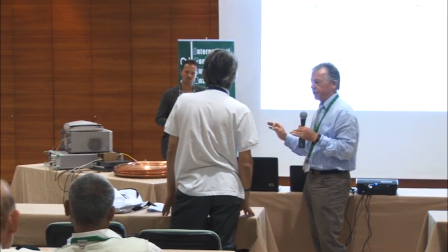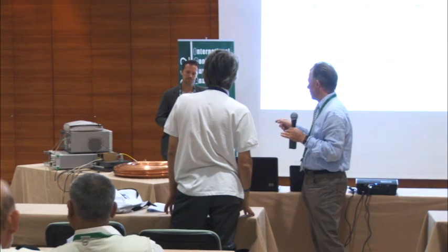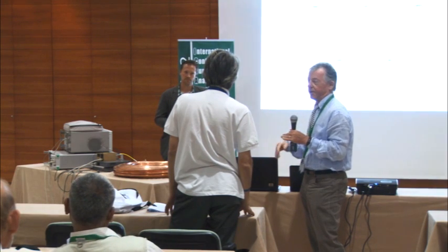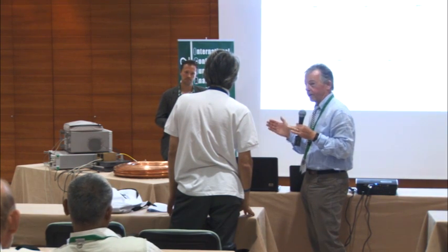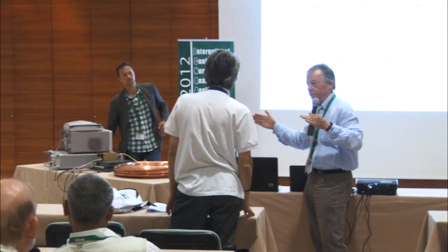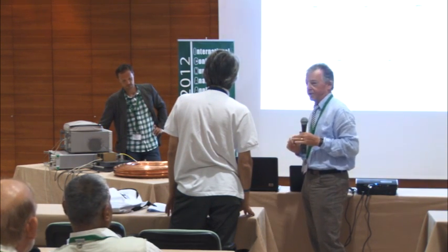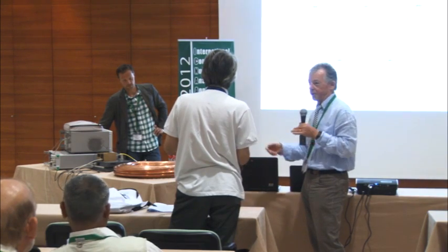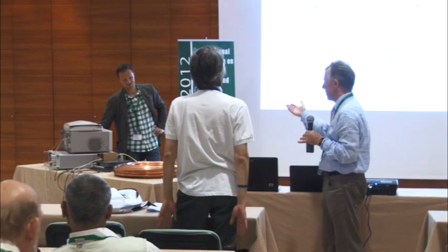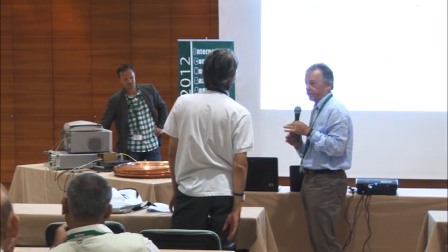Therefore, the engineers use this only, let's say, from 8 to 12 gigahertz, this size. And if you have a longer wavelength, a lower frequency, then you have to use a larger diameter, cross sections, and so on. We can measure only between 8 and 12 gigahertz. Otherwise, we have higher modes.